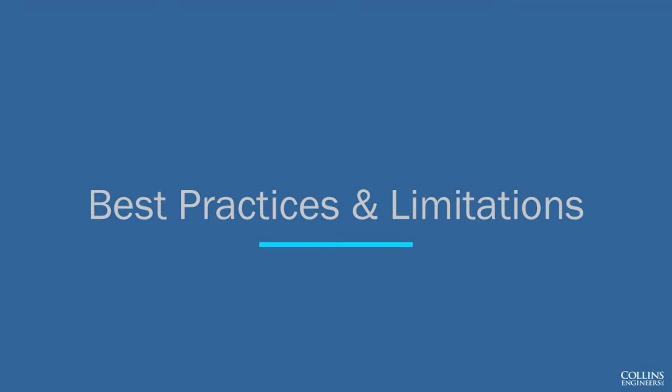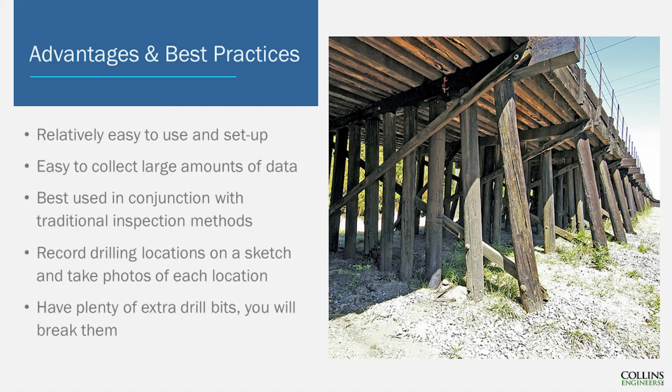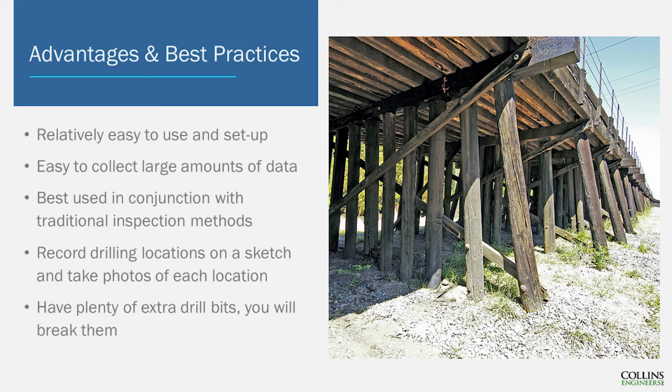Best practices and limitations. Basically the best practice is to use these in conjunction with traditional inspection methods. But it is easy to use and set up. It's easy to send somebody out and get a lot of data pretty quickly. You're going to want to record the locations of everywhere you do the drillings, preferably take a photo of each location too, and have plenty of extra drill bits. So there are lots of little nuances an inspector will learn if they do a lot of these.